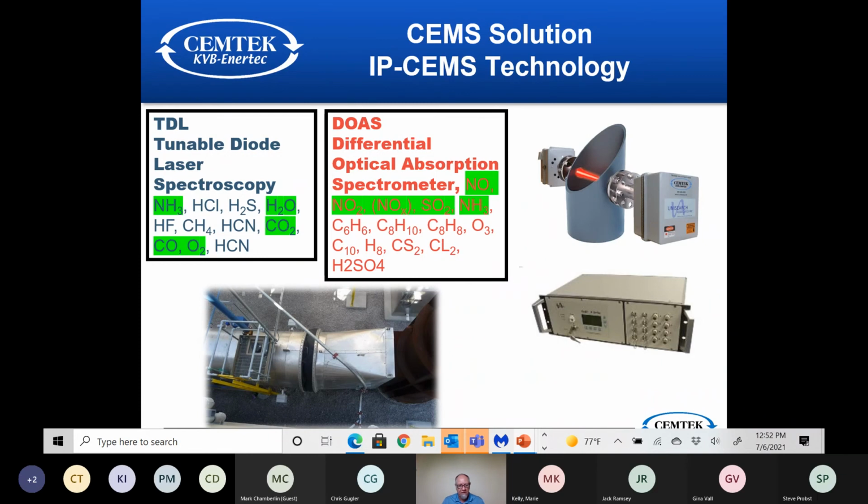So I have a lot of CEMS experience. We would have had to adjust those analyzers multiple times. There's been no maintenance other than wiping off the lenses a couple of times, and that was because of the cold weather. The only thing we did change was the UV lamp. It's got a lifespan. This was a demo unit that had been used in multiple other places before it went there. It had reached the end of its life. It was a 5-minute change out to put in the new UV lamp, and we didn't even have to do anything. Just put the lamp in, powered back up, and within 30 seconds we had an accurate NOx reading that matched the CEMS. Didn't have to change anything.